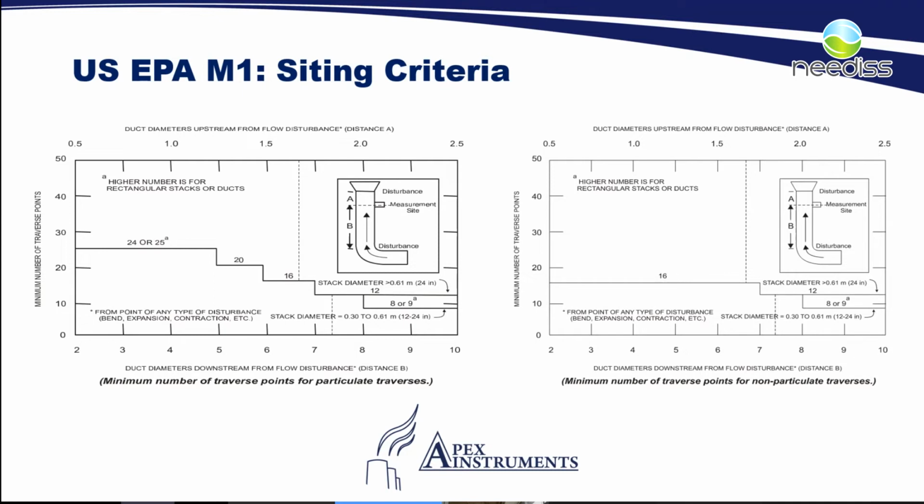In terms of the measuring console, unfortunately, it's not possible to use your regular isokinetic console because it only has 2 pressure lines coming in for your S-type pitot. And at minimum for our 2G, we need a 3rd pressure line, and for our 2F, we need 5 in total. So unless you want to theoretically sit 2 or 3 isokinetic consoles side by side, it's really not possible. So you would need a new device to be able to perform these methods accurately.